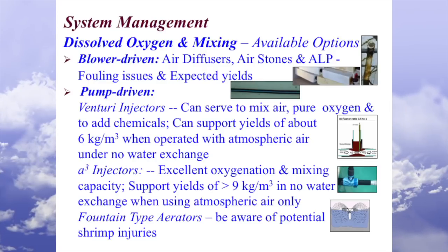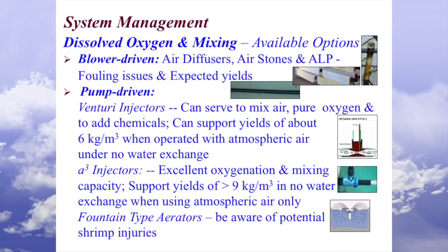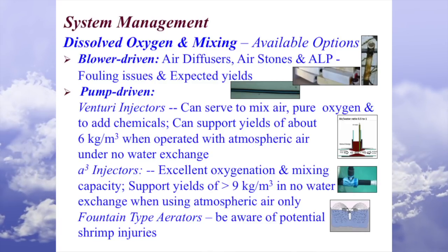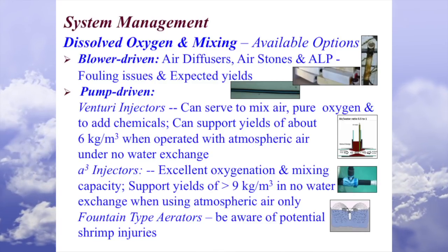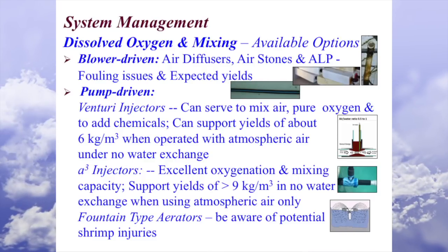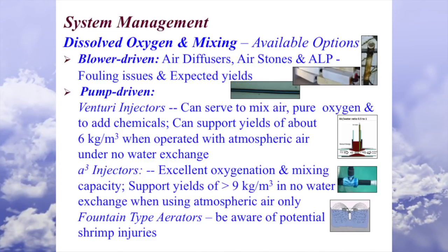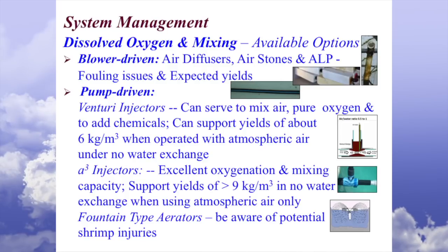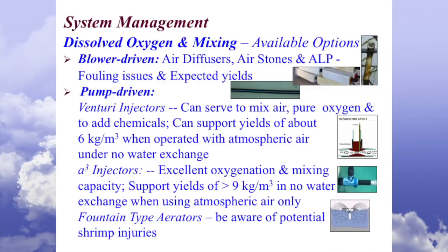Bringing oxygen into the water, there are different ways you can do it. Air blower with an air diffuser, airlift pumps, different methods of inducing oxygen into the water, but there are some limitations in terms of the biomass capacity and carrying capacity of these methods. Other methods are the Venturi type, whether it is a true Venturi or the A3 injector.